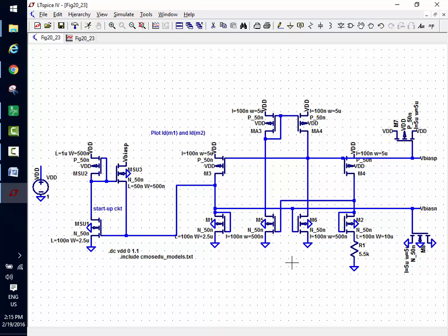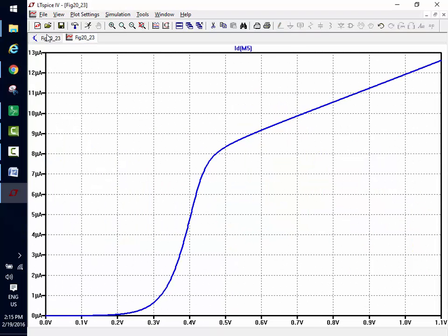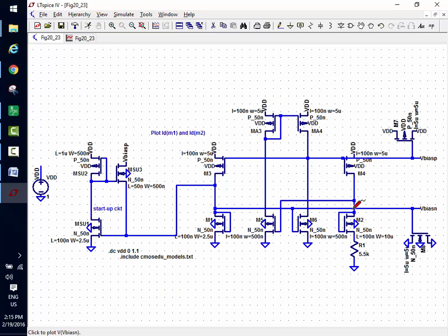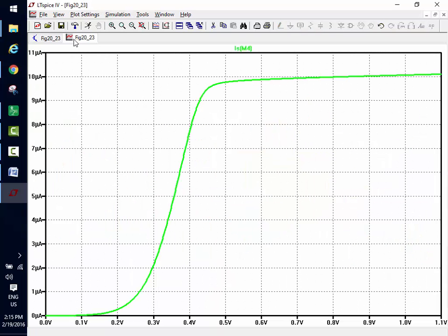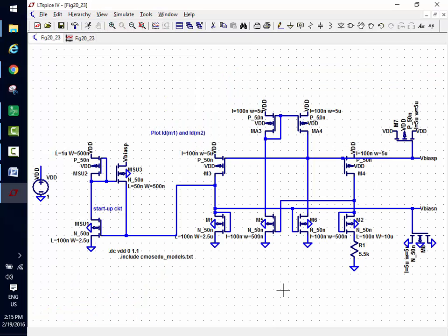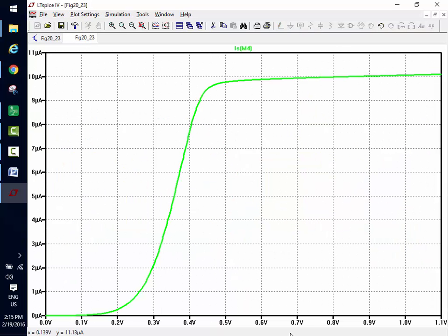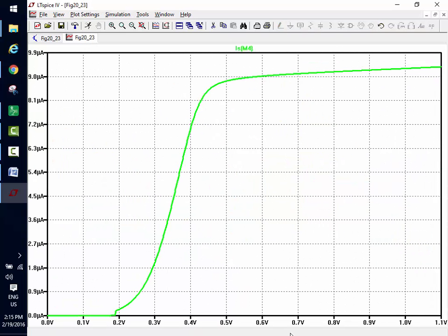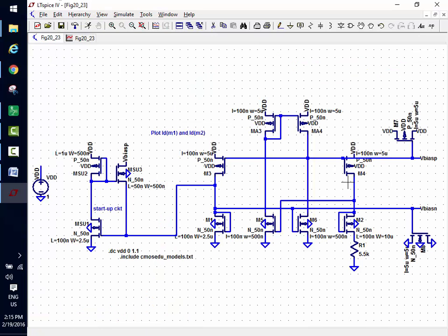Okay, so if I rerun the sim, I look at that. Oops, I don't want to plot that. Let's plot the current that flows in here. There it is. If I rerun and take a mental, with your mind's eye, that picture, I've reduced the size, which lowers the current. Less power dissipation increases the gain. What happens? I can't tell if it's that much difference. But the gain should go up, and it should be flatter, but the scale changed, so can't really say.